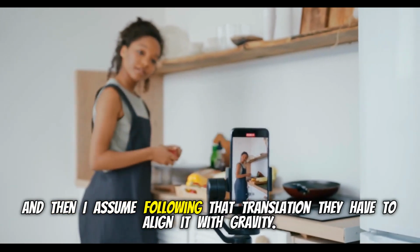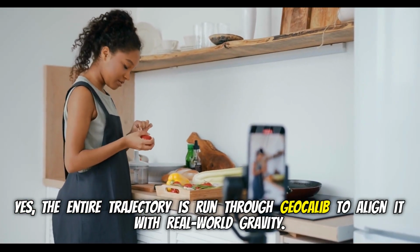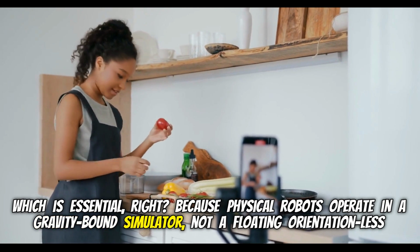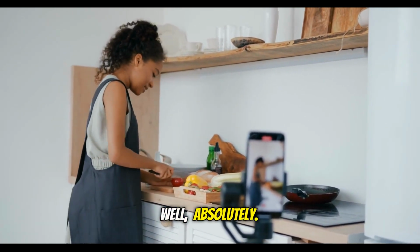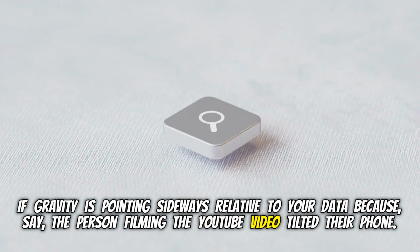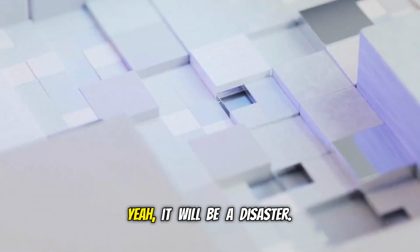And then I assume, following that translation, they have to align it with gravity. Yes, the entire trajectory is run through GeoCalib to align it with real-world gravity. Which is essential, right? Because physical robots operate in a gravity-bound simulator, not a floating, orientationless camera frame. Oh, absolutely. If gravity is pointing sideways relative to your data because, say, the person filming the YouTube video tilted their phone, the physics engine will immediately collapse the simulation when you try to retarget the motion. Yeah, it would be a disaster.